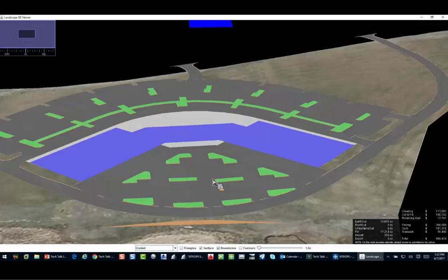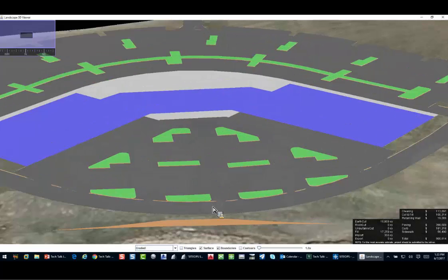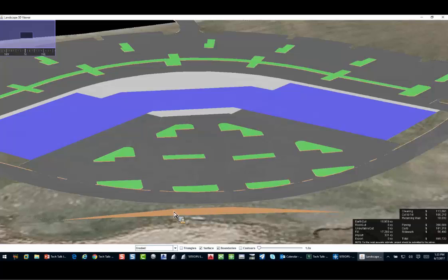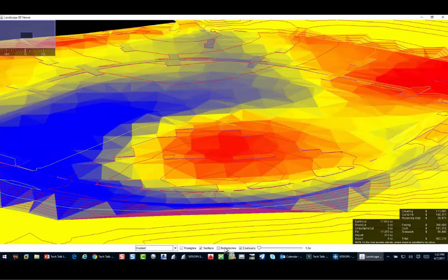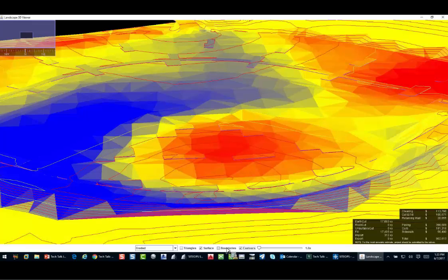And if we zoom in now, you're going to see that little tan area right there. That's a wall. And it's tapering up and down because, again, it doesn't need it out in the outer area. It can come in and grade. And you can see cut and fill. It looks like it's 1, 2, 3, 4, 5, about 6 feet tall. So good. We don't even have to have a structural wall. But the difference is it went up to $902,000. So it's about a $60,000 difference between the two designs.